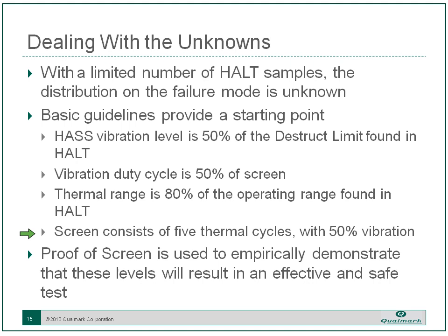I like to set up 5 cycles primarily because it gives you the opportunity to tune your screen in production later. You really get a solid idea of how effective the screen is by watching when failures drop out after you've run a few thousand units through your screen. If everything's dropping out in the first 2 passes, then you know you can start backing that screen off and save some time and money.